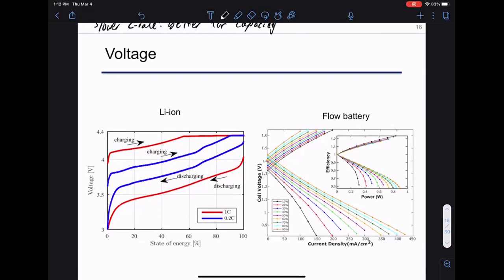The way it works is you have a BMS, a battery management system, that looks at how fast you want to charge, and then the power electronics converter. Let's say you have a buck converter, and the buck figures out the right voltage that appears at the battery terminal, and that determines the C rate. Okay.